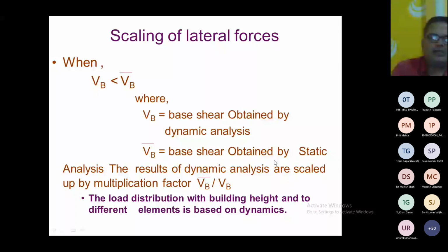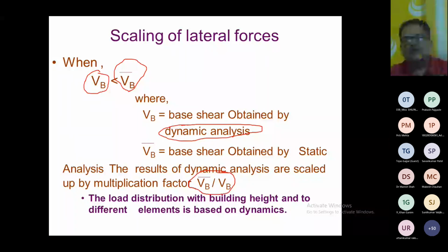But here the important thing is this: if the base shear obtained from the dynamic analysis is less than the base shear obtained from the static analysis, then we have to apply this multiplication factor to the results we are getting from the dynamic analysis, right? So that is very important.